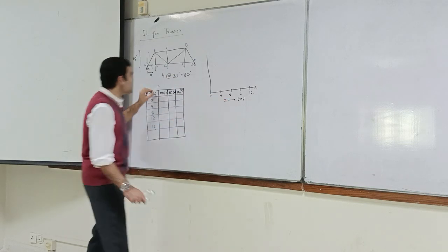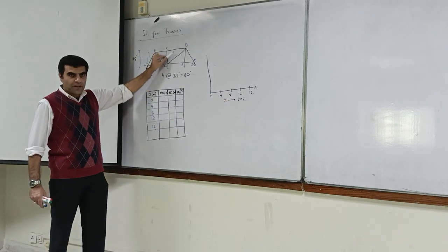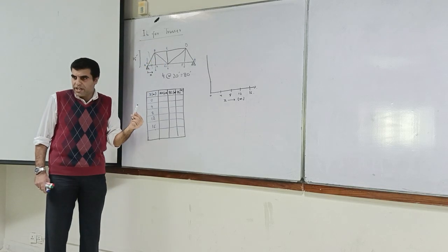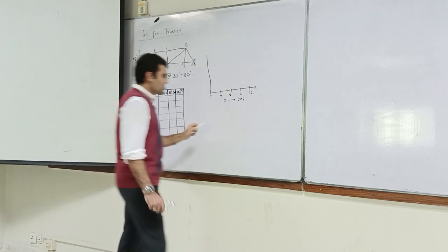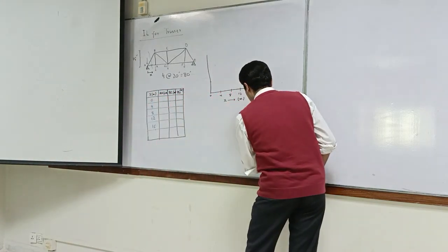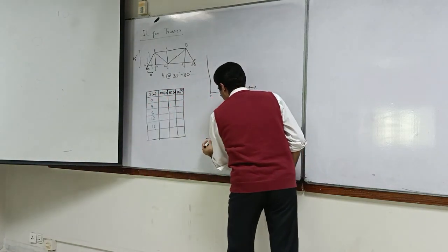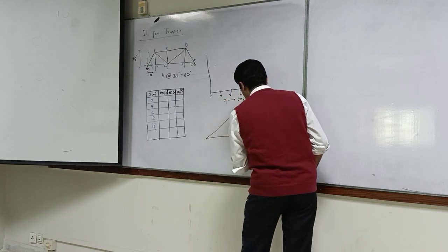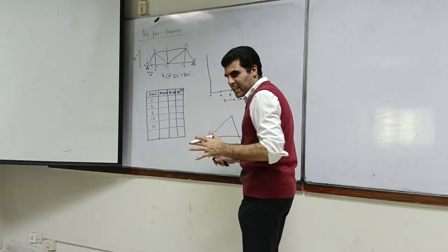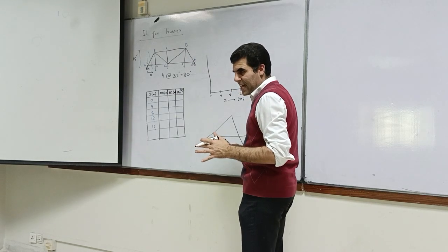Okay, and in the case of braces, a brace is like a shear. So you will see that as the load moves, it will be something. For the brace, normally your influence line diagram will become something like this. Okay, that is a common influence line diagram.